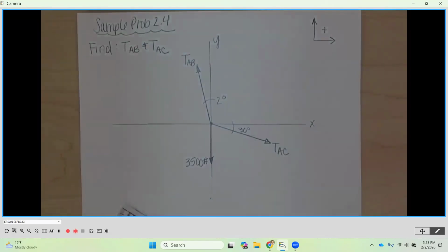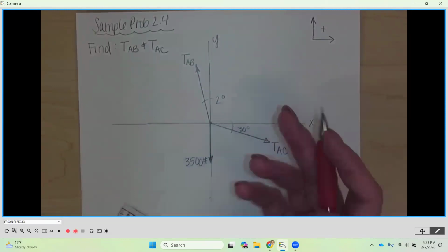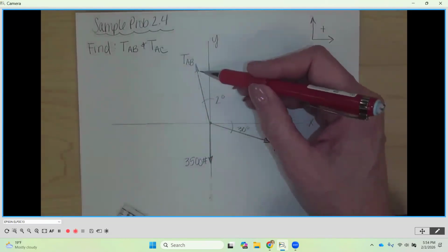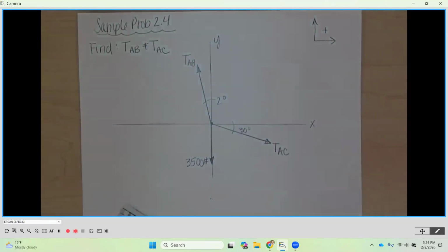So all we did for this illustration is show just the forces that are acting, with their common point being this origin, which is representing point A. And we are putting these forces along their lines of action, or in this case, along the cables that they would be on. Okay. Now, they are all pulling away from that origin because you'll notice that we're using the variable T. That means that there's tension in that cable.